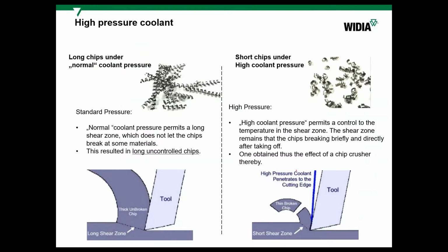And pressure. Also, some of you asked about coolant. Coolant can be used differently depending on what material you are machining: aluminium, stainless steel, what type of wear you are faced with, and usually coolant should be delivered directly to the cutting zone. Also, if it's delivered with high pressure, for example, 100 bars or 300 bars, it changes the cutting process. It helps chips to be broken, to make this machining easier and the tool life longer.